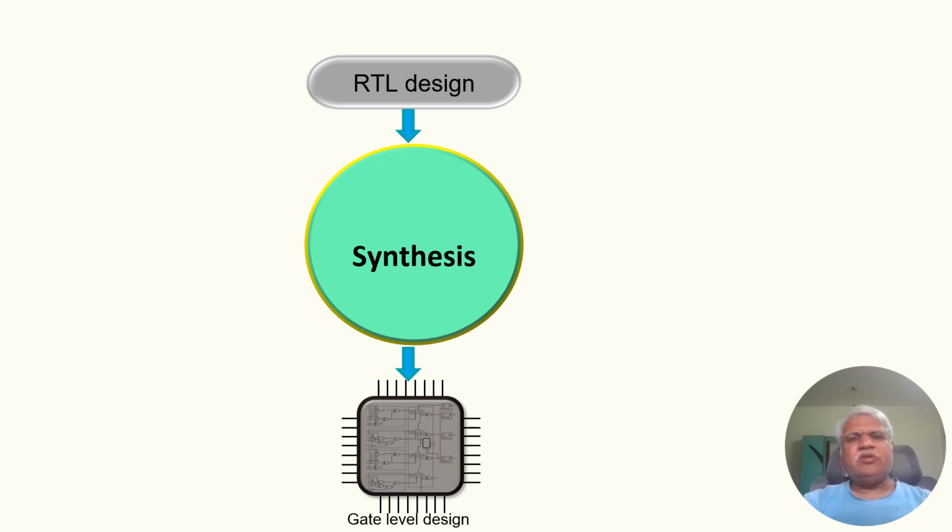Largely, in the synchronous operation, the design, when implemented, will contain a set of registers, especially implemented either as a D flip-flop or any other type of flip-flops. It can be RS flip-flops, T flip-flops, different types, but usually the D flip-flop is preferred.